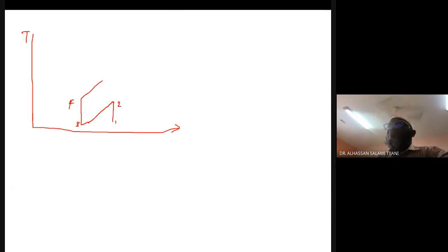So we have, this is the heat input side from 4 up to state 5. And there will be expansion in the first turbine. So we'll have state 6. Okay. So now, again, there will be reheating up to state 7.